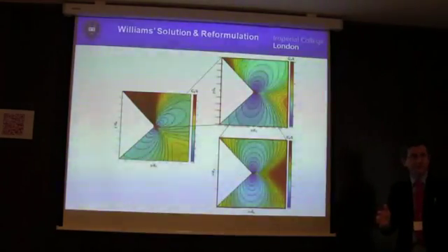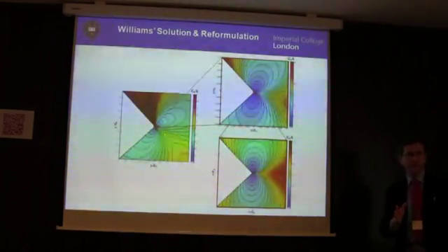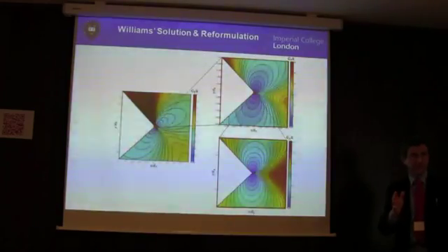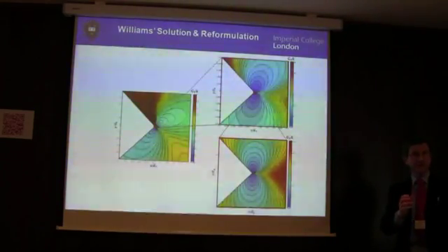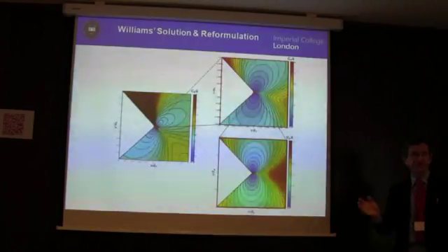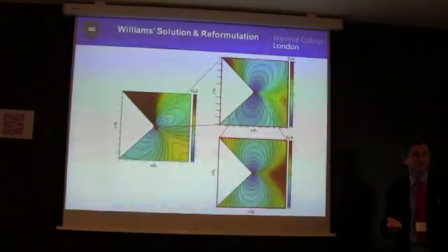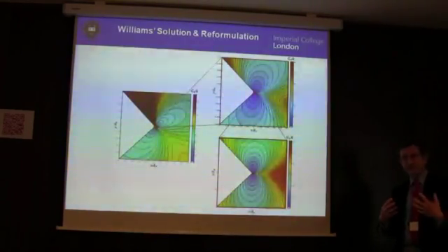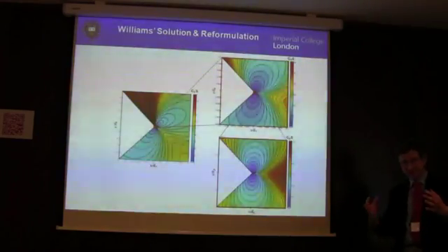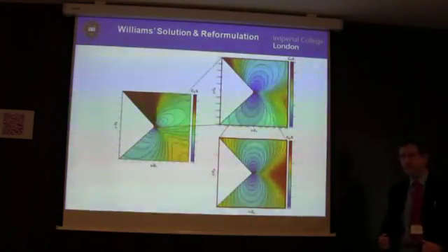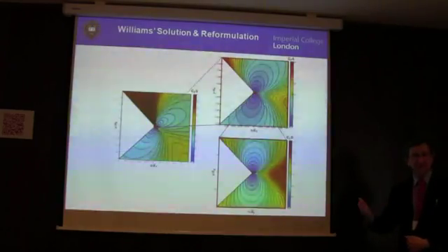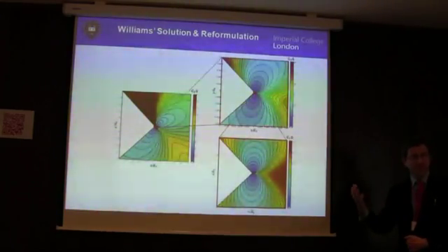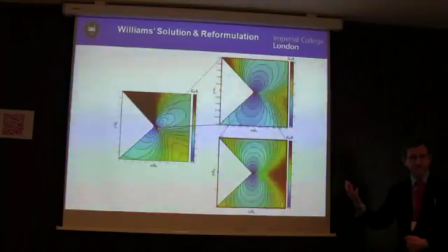If you had a problem in which you had only the mode 1 load, or the mode 1 solution excited, then of course at every scale you just get a mode 1 stress field. But if you have a mode 1 and a mode 2 present in the external field, then you'll get something where you're going to get this combined result at the notch root.